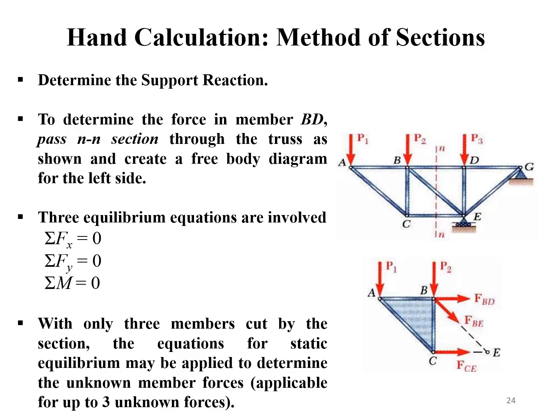The internal and external forces must be in equilibrium, and so we can apply the equilibrium equations to solve the internal forces. When choosing how to cut your truss, remember that we only have three equilibrium equations. If you cut through too many members, you will have too many unknowns and not enough equations. Normally, we choose the side that looks easier to solve because there are fewer forces. The method of sections is best used when we have a truss which has a lot of members, but we are only interested in the loading in a few specific members.